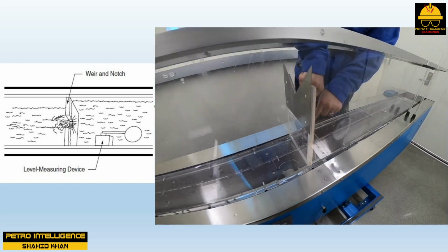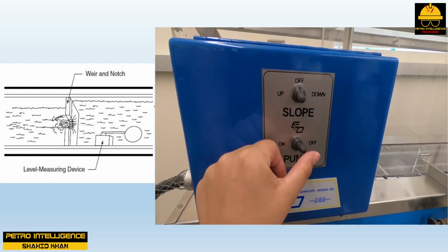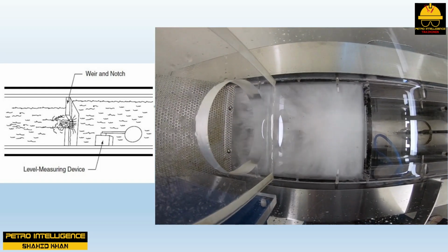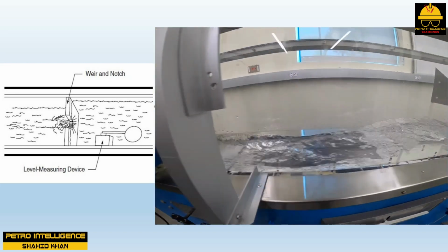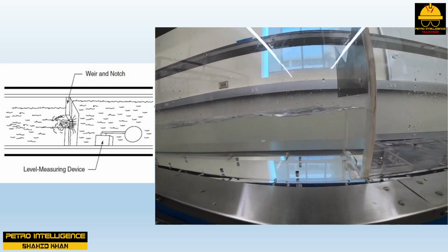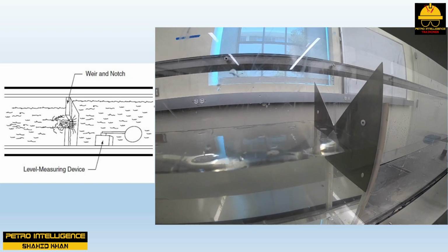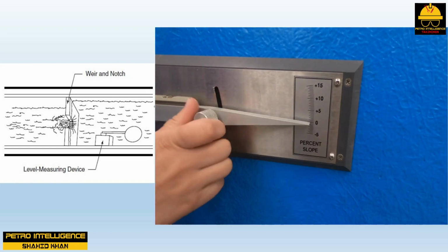There is a direct correlation between the liquid level and the flow rate. The lower the level, the slower the flow. Flumes operate under the same principles as a weir but are used for higher flows. The flume is a narrow, sloping pass that funnels flow. At the inlet of the flume, the water level rises and is measured by a level measuring instrument that converts the level to a flow signal.